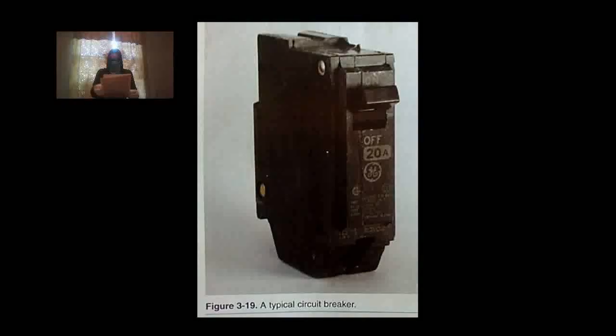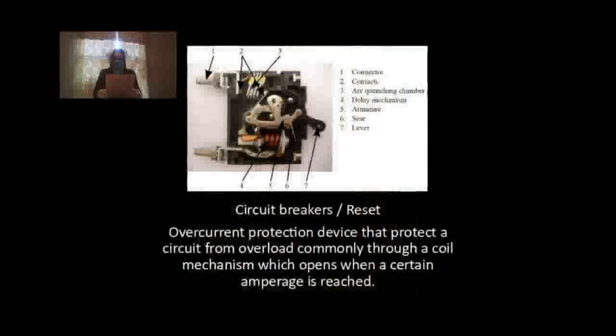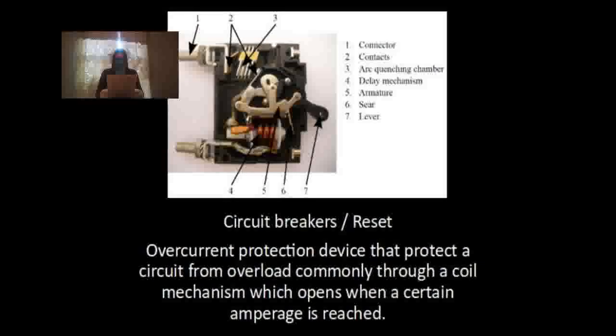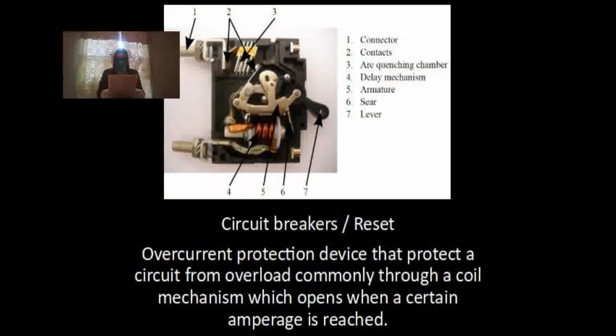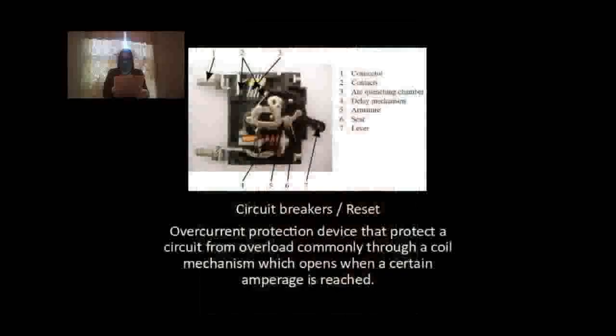Circuit breakers are produced with two different tripping methods. One method uses bimetallic strips. A bimetallic strip is a metal strip made of two different types of metal. Different metals expand at different rates. Heat generated from the overload condition causes the bimetal strip to expand, and the different metals expand at different rates. This causes the breaker's trip mechanism to bend and break contact. Some trip mechanisms are adjustable to allow a more precise trip current.